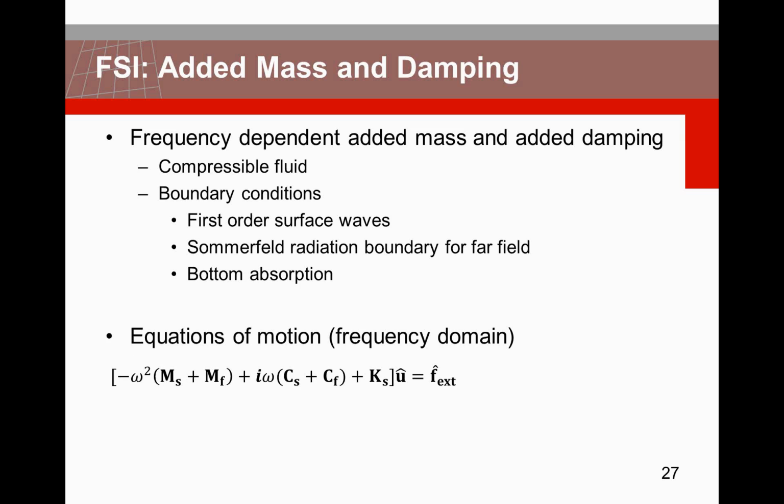So it is not possible in a standard transient dynamic analysis to account for compressible fluid, because it gives frequency dependent behavior which cannot be handled in a standard transient dynamic analysis, as we also will see later.